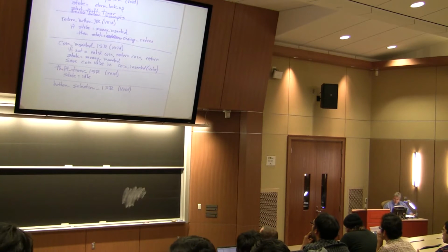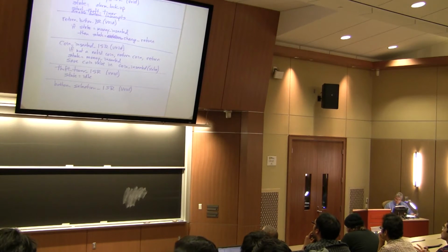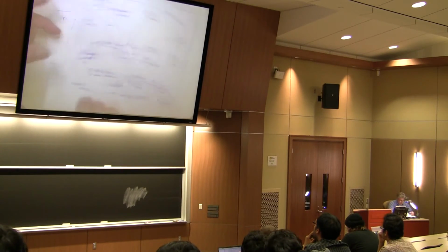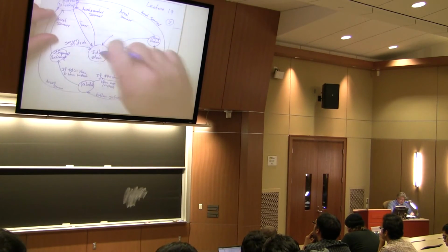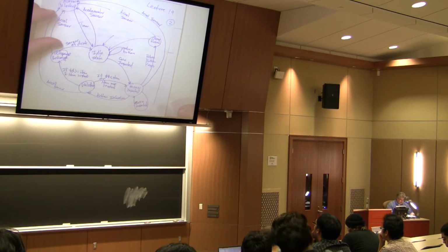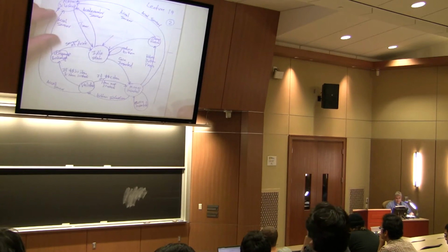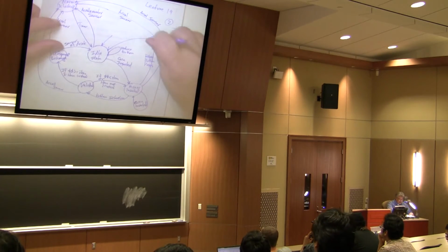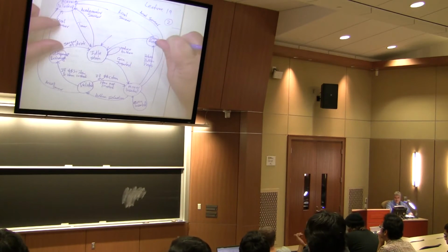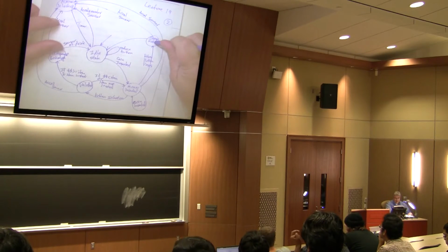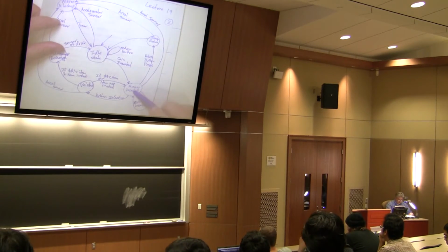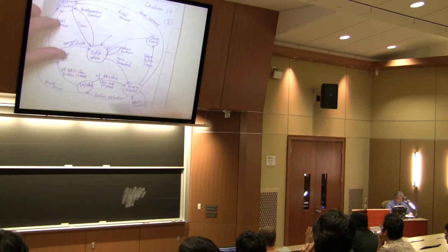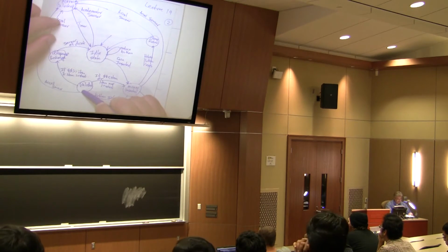And as a part of the button selection ISR, what would happen? Well, what if you're in this idle state and somebody pressed a button? What should happen? Nothing, all right? What if you're in the change return state? Really, nothing happened, right? What if you're in the money inserted state? Oh, that's when you want to go to the validate state, right?